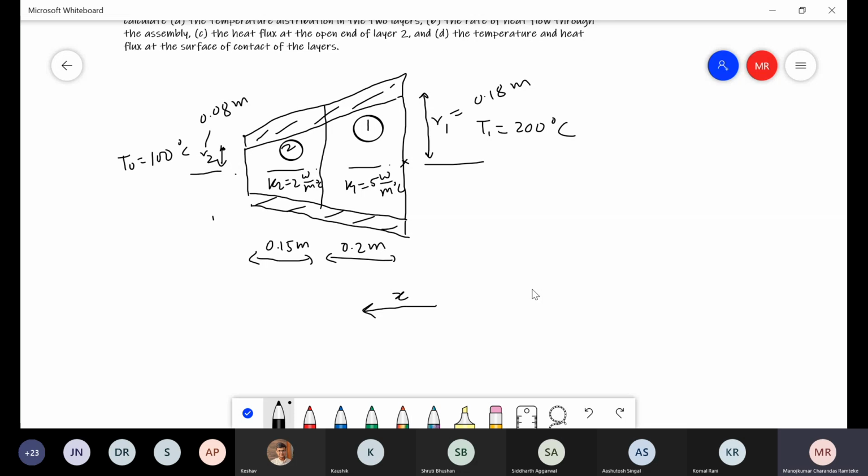So rate of heat input is going to be area, that is pi r square Qx at x, and Q out is again pi r square Qx at x plus delta x, and that should be equal to 0. So after rearranging, what you should be able to get is d by dx of r square Qx equals 0. That is what you are expected to get.